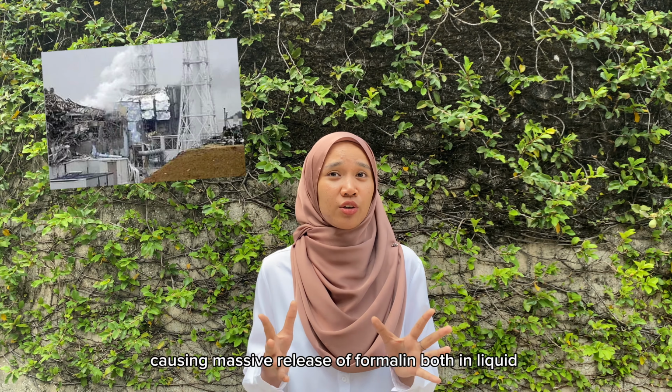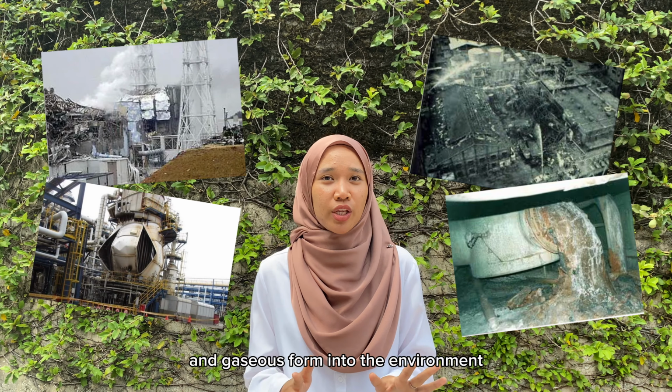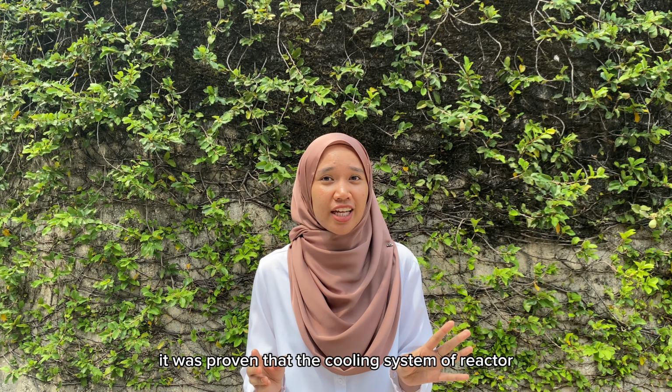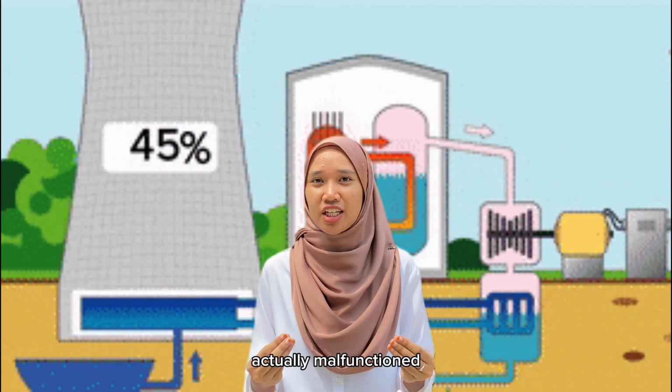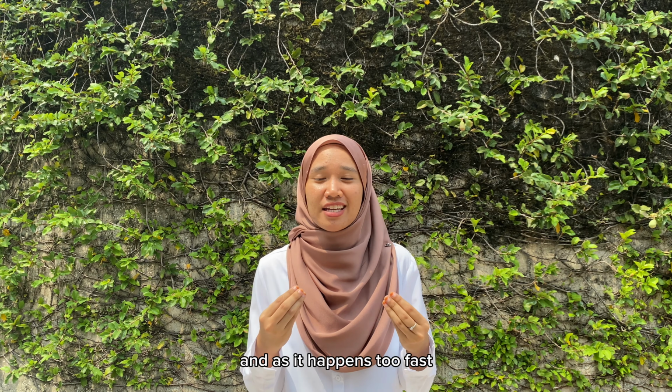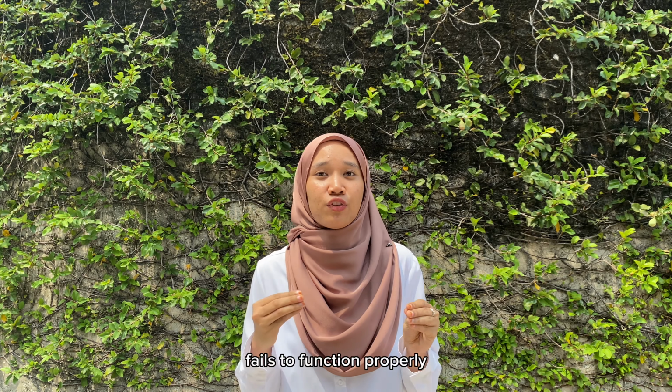In 2020, a reactor ruptured, causing a mass release of formalin, both in liquid and gas form, into the environment. What exactly is the problem here? It was proven that the cooling system of the reactor actually malfunctioned, causing the temperature to rise uncontrollably. And as it happened too fast, the pressure relief valve failed to function properly.